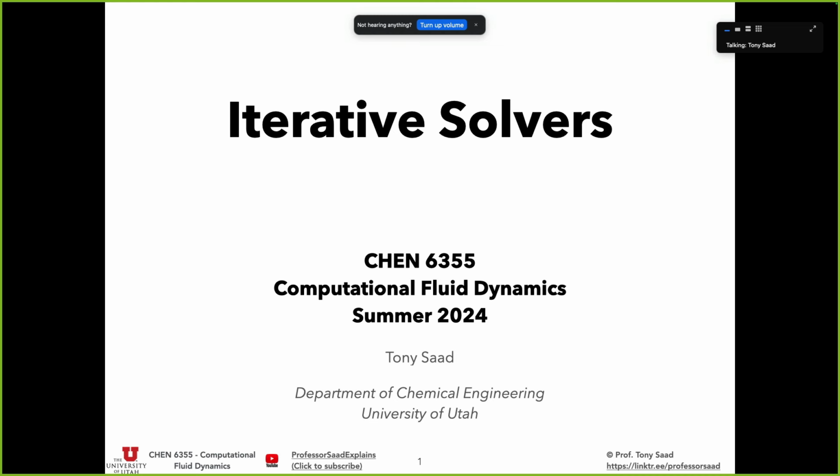And in practice, in many cases, that pressure solve could cost anywhere between 70% of the total calculation down to 30% when you have a lot of physics going on, but it's a pretty big piece of the computational fluid dynamics cost when you think of computational cost. So as we get into part two of the course where we're going to dig under the hood, I figured that would be a good segue: to start with linear solvers and start by asking the question, can we make the linear solver faster, so we can get faster solutions and reasonable solutions for these problems?